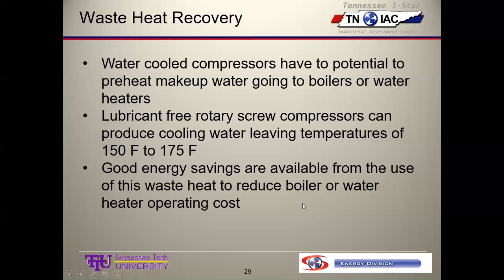And of course, you've got to have consistent compressed air demand and makeup water demand on your boiler, but it was a big plant and that worked out well for them. So it took that 70, 80% of the electrical energy that's converted into heat in the air compressor and put most of it into the boiler to reduce the natural gas purchase. That's pretty smart thinking.